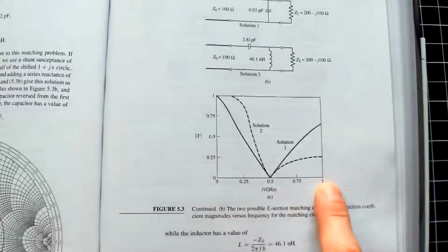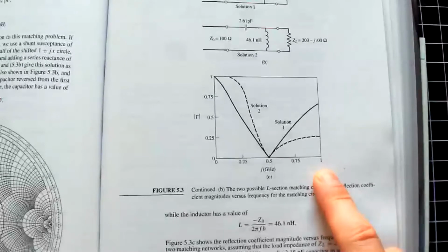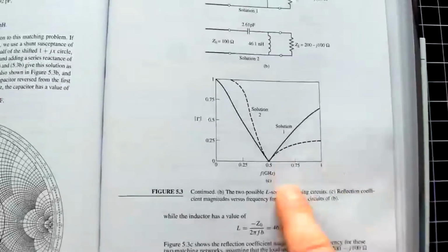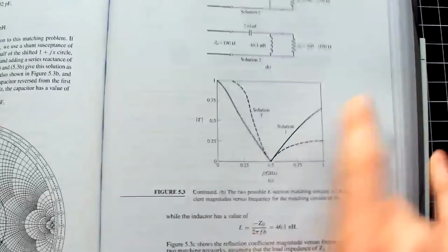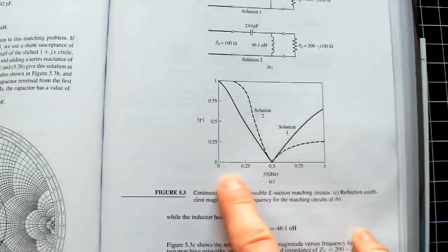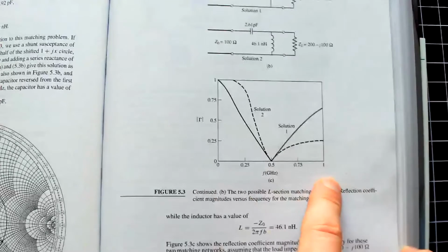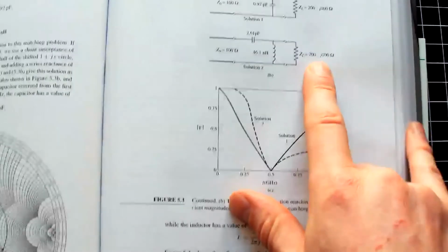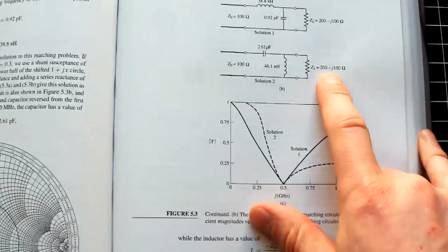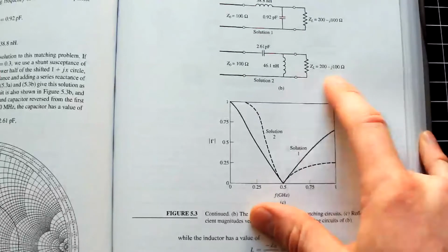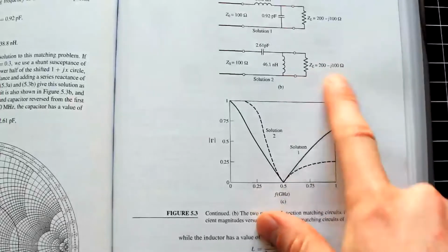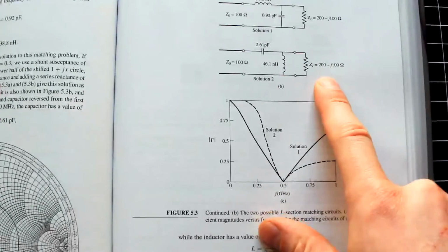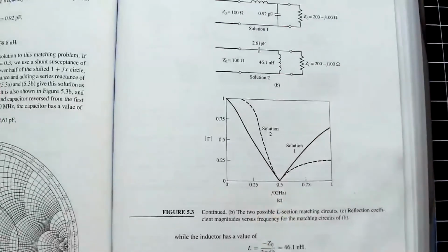And that's good from a pedagogical perspective. But I remember chuckling, like, oh, how adorable, he thinks the load impedance won't change with frequency. So it's a good exercise to do, but one of my little questions is, do you really think there will be a load in practice that is going to be constant over frequency? A classic example would be something like an antenna, where that impedance will not be a constant value. It will change at every frequency you excite it at.